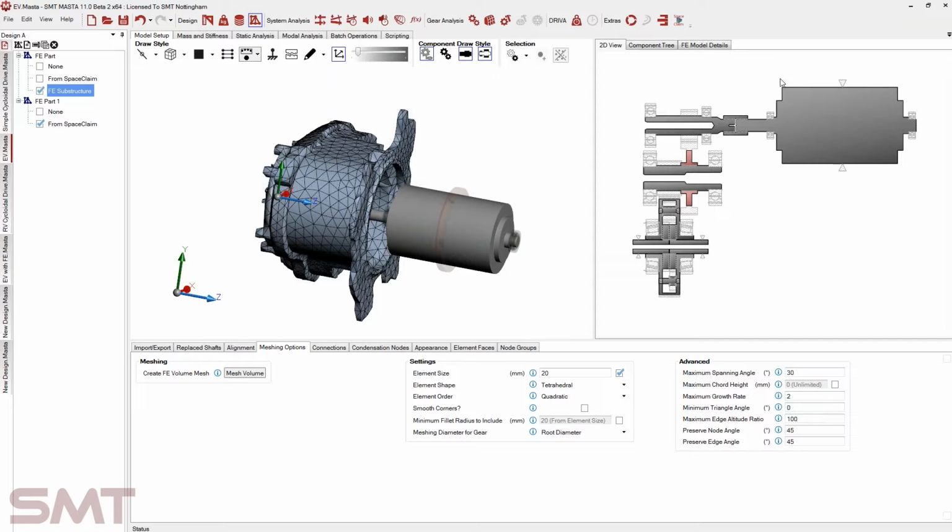Okay, and then there's another question there, which is, can you give us a list of modules of Spaceclaim that would be needed? I was trying to find out the information for Spaceclaim itself and what you would need within Spaceclaim. I don't think you need much more than just a basic license, to be honest, to actually use this functionality in Spaceclaim. If you want to use the actual Spaceclaim meshing, I think that's a bit of an extra license on their end.